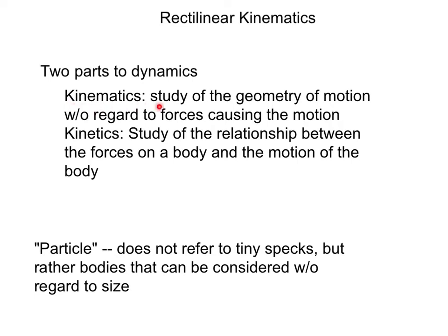Kinematics is the study of the geometry of motion without regard to forces causing the motion, and kinetics is the study of the relationship between the forces on a body and the motion of the body. So kinematics is how the object is moving, and kinetics is what is causing it to move.